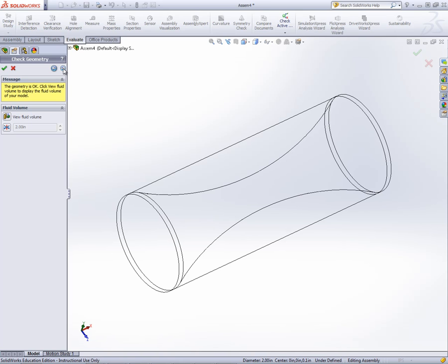If you have an error here, you need to go back and make sure your geometry is right, that you don't have a line over a line or a small gap, and make sure that your lids are matched up to the very ends of the venturi. If you followed the previous module, you shouldn't have any of these problems. We'll left click on the next little arrow again. It says, what are we going to use for the analysis, air or water? Well, we'll use water. So we'll left click on the little arrow again.